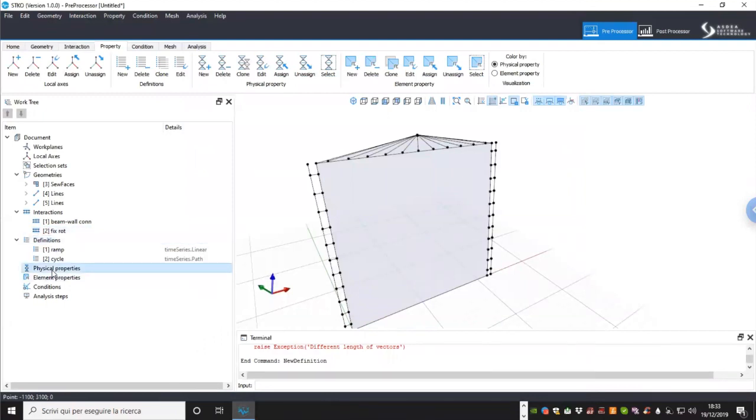Now in this case, we are going to create a three-dimensional concrete model, which actually is not available in the official OpenSees version because it is a constitutive model that we developed. So if you download the version of STKO with our version of OpenSees, you will have this model. And it is based, yeah, of course, you should be outside of Italy because we cannot redistribute it in Italy.